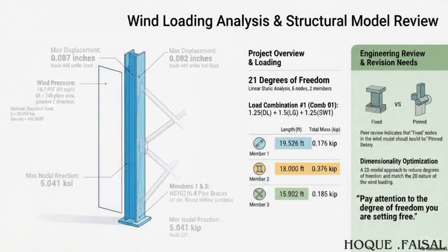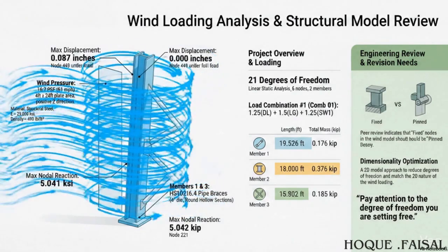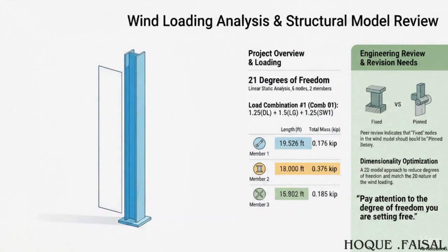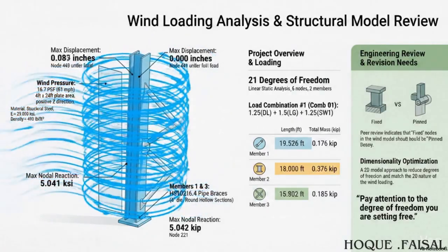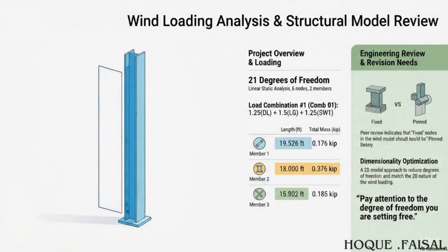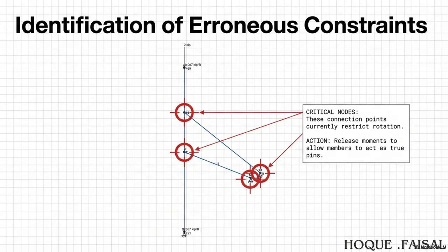And this very report proves the point. Just look at the supports table. It's a mix of codes. We have FFFFFR for some of the support nodes. So fixed, released. 5 Fs and an R. Try to visualize what that means. Which axis is released? Is it the rotation around Z? Is Z the vertical axis or the horizontal axis in this particular software's coordinate system? The report calls it positive ZDIR-WL, so Z must be the wind direction, I think. See, we're already getting confused, and we're just talking about it.